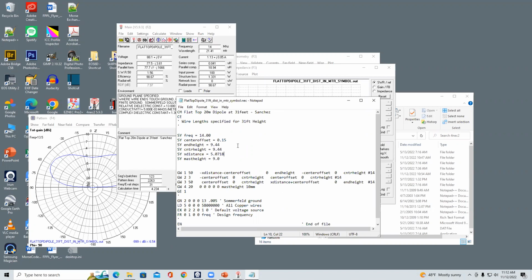So we'd have to be adjusting both of them up and down as well. I was just curious, since the inverted V had a lower SWR than the flat top, whether you had looked at going up and down on a T antenna. Oh, I think I understand. So you're saying I created the inverted V by lowering the ends, which, since it's closer to the ground, may be why the SWR is lower. That's the basis of my question.